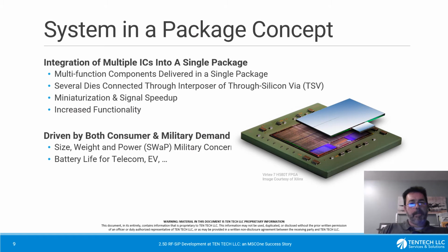Now we're going to spend a little time talking about SiP, a system in a package, and what it is. Basically, this is a bunch of components that should be distributed on a PCB that are actually all brought together in a smaller package, performing the same task, and sometimes even more than a traditional PCB. And instead of having one die, one substrate, another die, another substrate, all this put together on one board, you have one little substrate that contains all of this. So this offers many benefits.